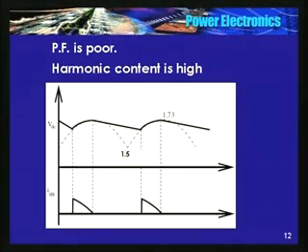See here and here. Okay, see these are of 60 degrees, so they conduct for a very small duration. So basically the source power factor is very poor. Okay, so there are going to be predominant harmonics. What is another limitation? As the input voltage to the diode bridge changes, the DC link voltage also will change.